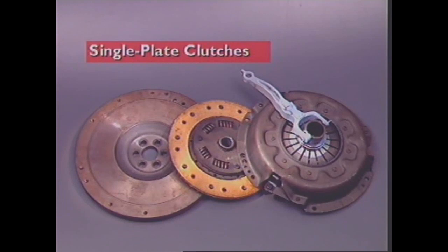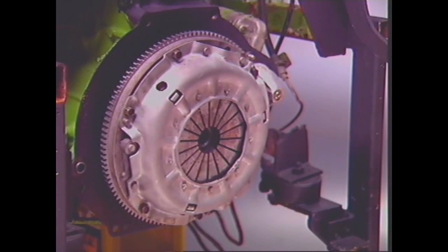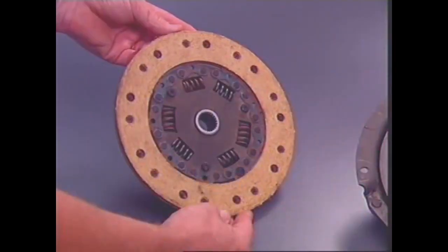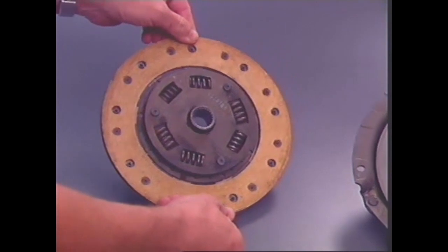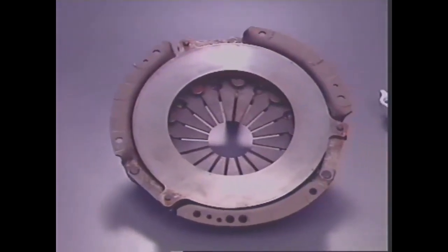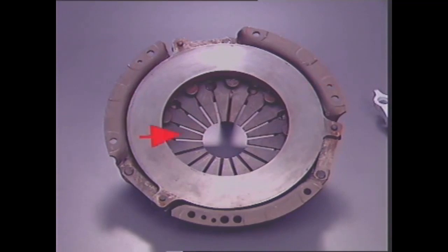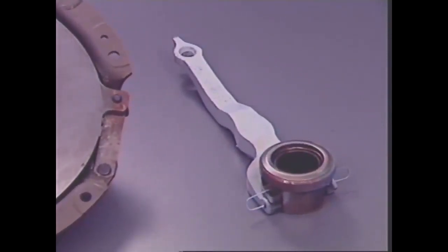Most light vehicles use a single-plate clutch to transmit torque from the engine to the transmission input shaft. The flywheel is the clutch driving member. The clutch unit is mounted on the flywheel's machined rear face, so that the unit rotates with the flywheel. The clutch unit consists of a friction-type disc with two friction facings and a central splined hub, a pressure plate assembly consisting of a pressed steel cover, a pressure plate with a machined flat face and a segmented diaphragm spring, and a release bearing and operating fork.